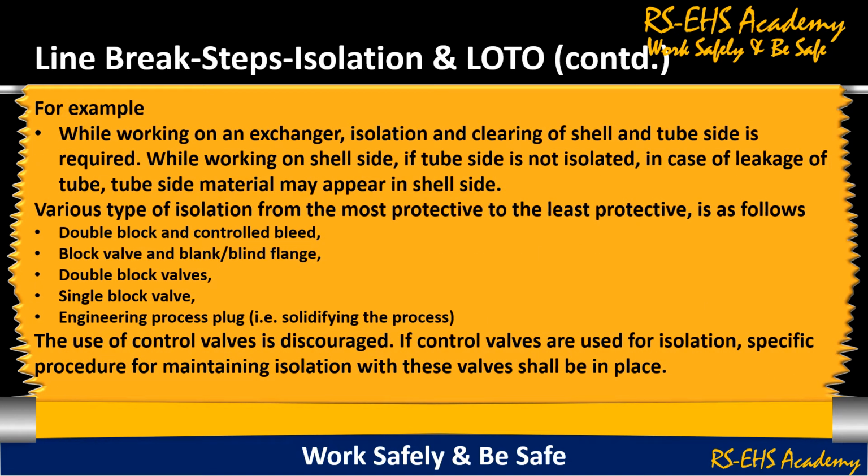Further to the line break step, isolation and LOTO. For example, while working on an exchanger, isolation and clearing of shell and tube side is required. While working on shell side, if tube side is not isolated, in case of leakage, tube side material may appear in shell side. Various types of isolation from the most protective to the least protective are as follows.